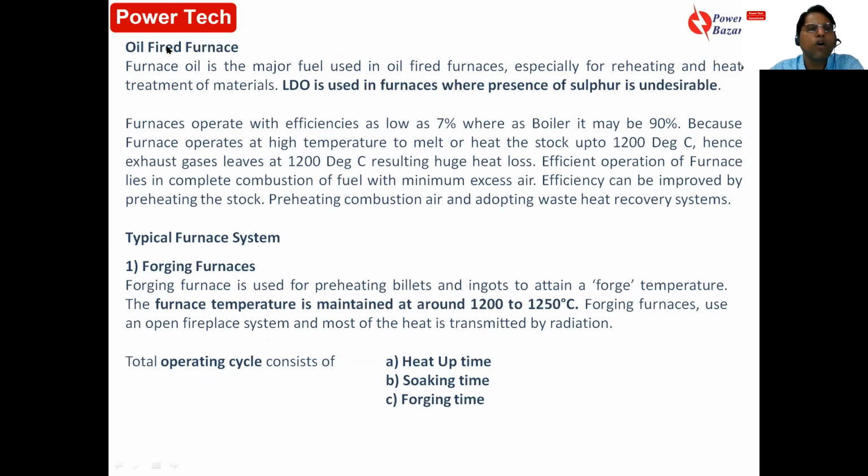Now let us come to an oil-fired furnace. In this case, furnace oil is the major fuel, and sometimes we use LDO because we don't want sulfur to change the characteristics of the feedstock or the charge material. So this oil is basically used for reheating and heat treatment of the materials.